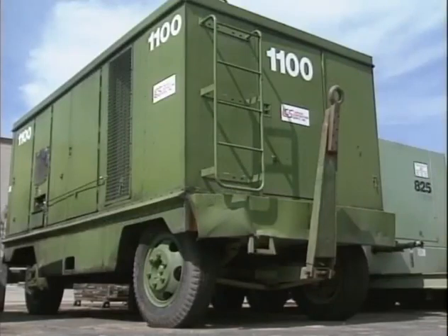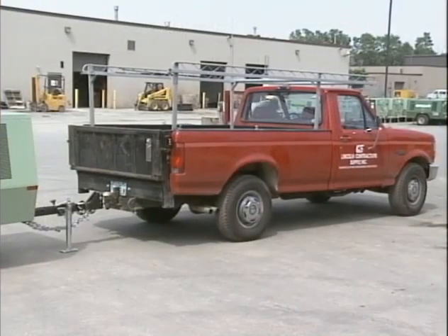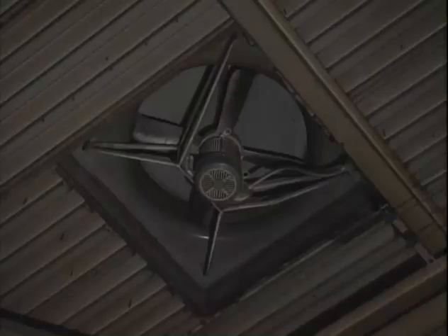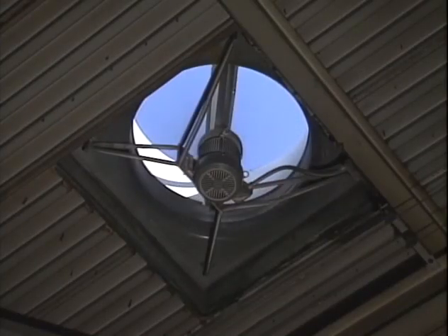When possible, stow hinged drawbars in the upright position. Keep feet clear of the drawbars at all times to avoid crushing accidents in case it should slip from your hands or otherwise fall to the ground. Move the towing vehicle well clear of the parked air compressor and erect hazard indicators, barricades, and/or flares, if at night, as appropriate. Exhaust fumes can kill. Do not operate an air compressor in an enclosed area.